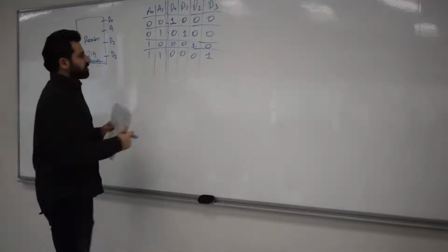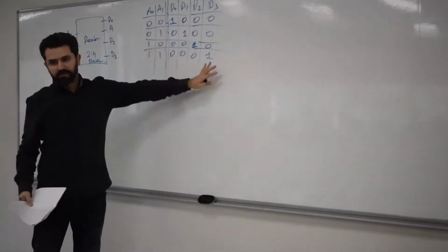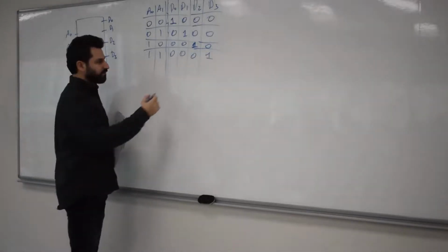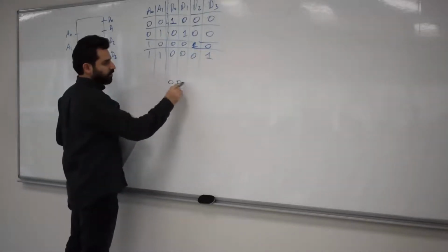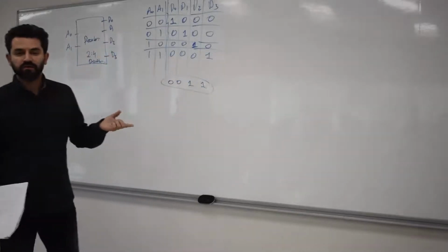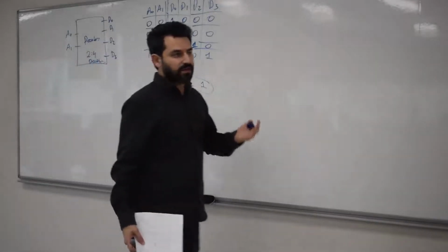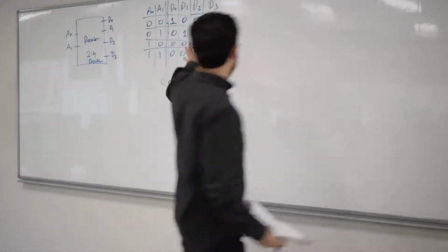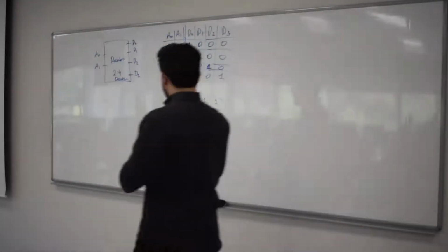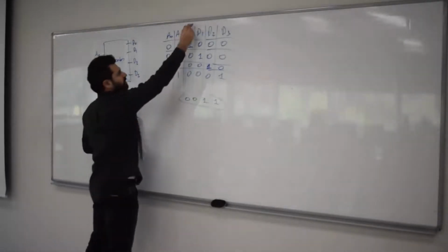And since the circuit generates these outputs, we assume, for instance, that 0, 0, 1, 1 would never appear because we design our circuit that way. So we don't need to worry now about the errors that we had in the encoder, because this was our input. Okay, so if you look now at D0, for example, so this is my D0.